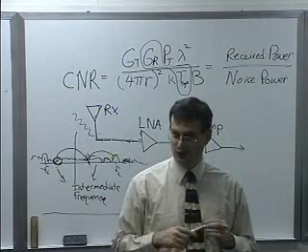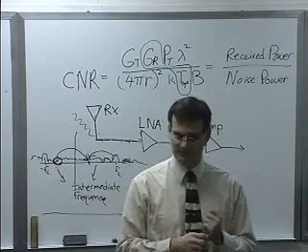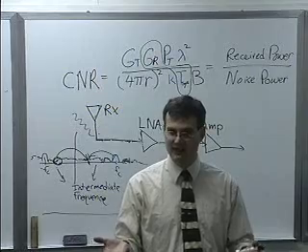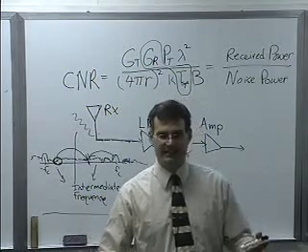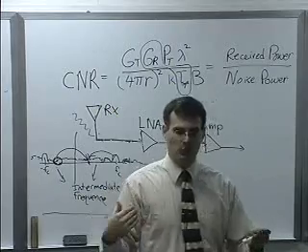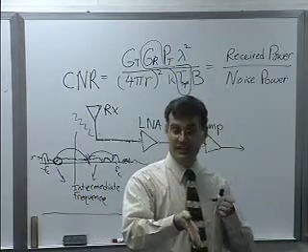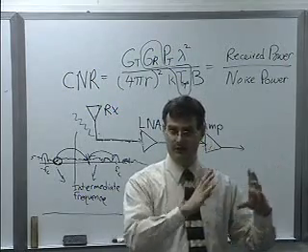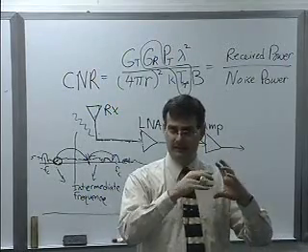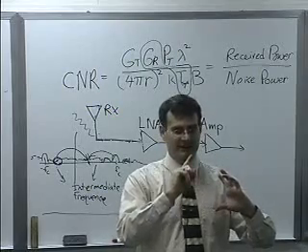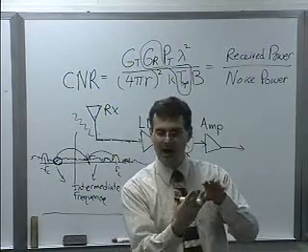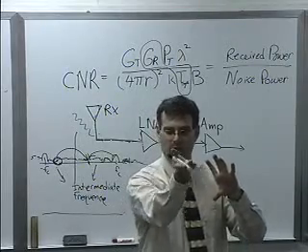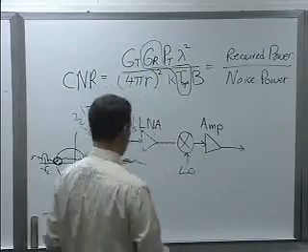Do you measure noise temperature of your devices? Quite a bit. So every device has some sort of noise associated with it, especially an active device. This is additional Gaussian white noise that will be added into the signal in addition to what has already gone through it. So the physical noise that comes in through the temperature that the antenna sees will combine with this device noise, and so the output will be basically even noisier than what you started with.